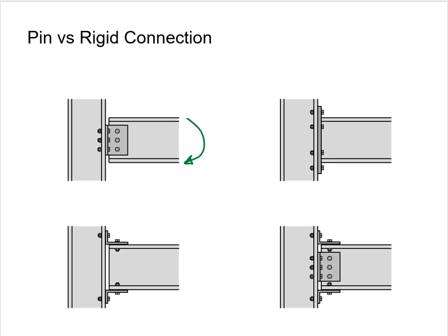be transferred. If we only connect this beam near the middle, at its web, when we try to carry moment, the bolts create a force couple with a small distance. That is not very effective for creating moment. However, if we connect the beam at the outer edges, the flanges, the distance between the forces is larger. This is much more effective for creating moment.